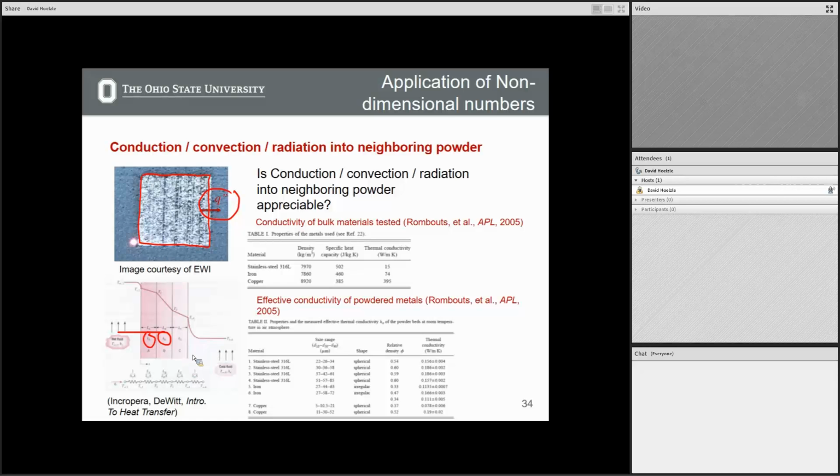And the main thing to mention here is that if one of these conductivities is really, really low, then we consider that to be a Neumann boundary condition, right? We can effectively say that that material has very poor heat transfer through it, so therefore the conduction is going to be very low in terms of heat flux.